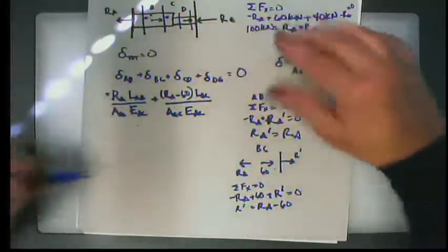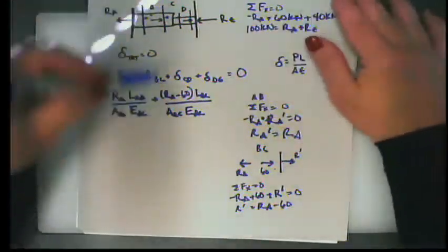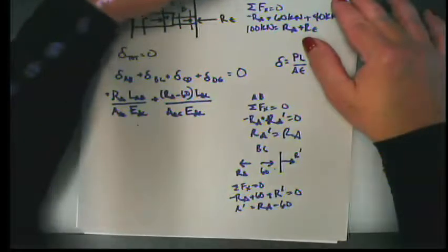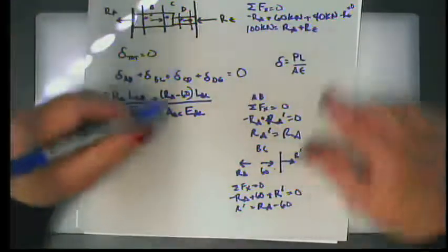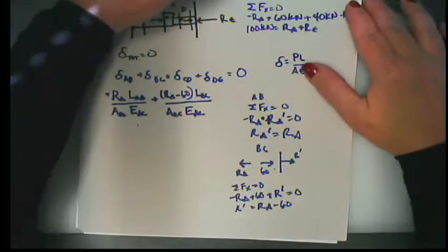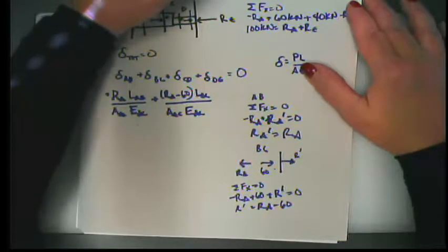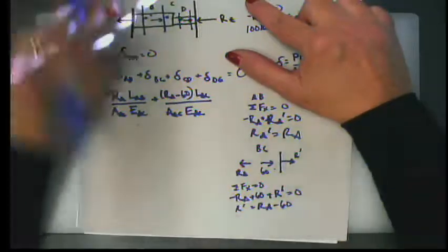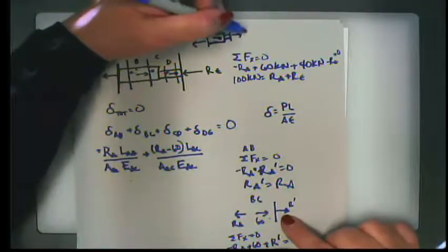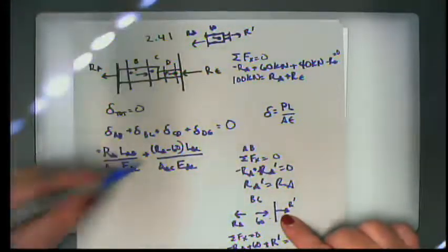Okay, so now let's look at C to D. Let's look at my cutaway at C to D. Well, my forces are the same. I don't have another force here. So if I cut away here between C and D, I'm drawing this like that. Okay, I still have R sub A, and I still have the 60 kilonewton force. Can you even see that? No, there we go. And then I've drawn this one positive. It's the same reaction, so I want to draw that the same way.